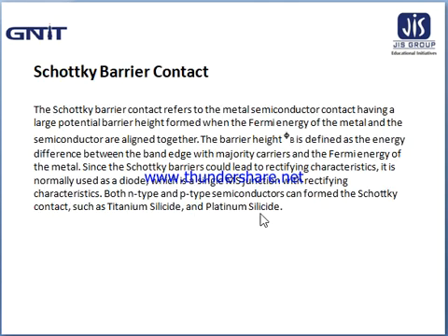Now, what about the Schottky barrier contact? The Schottky barrier contact refers to the metal semiconductor contact. Here, a large potential barrier height is formed when the Fermi energy of the metal and the semiconductor are aligned together.